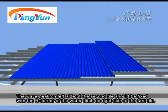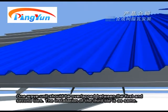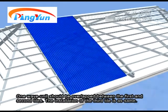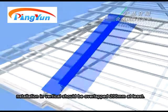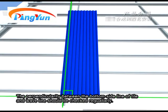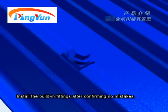The wave peak on the left side of the second tile should be fixed with the arc corner of the water ditch on the right side of the first tile. One wave unit shall be overlapped between the first and second tiles. The installation of the third tile is the same. Installation in vertical direction should be overlapped 200 mm at least. The perpendicularity between the bottom side line of tile and wave line should be checked regularly. Install the built-in fittings after confirming no mistakes.